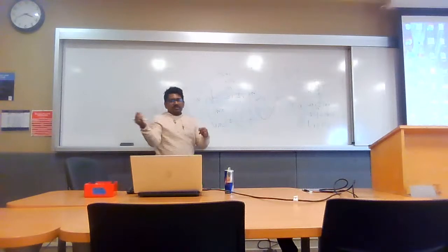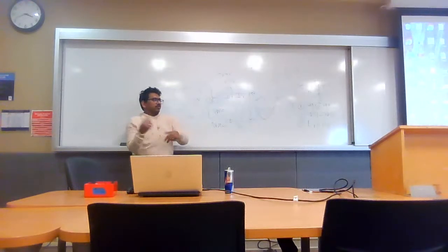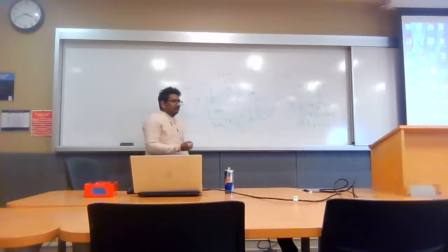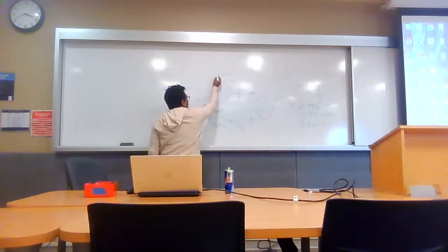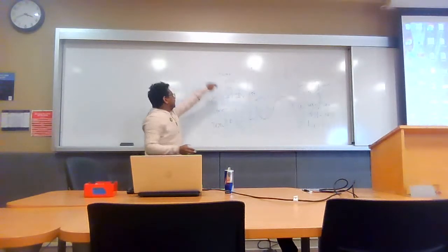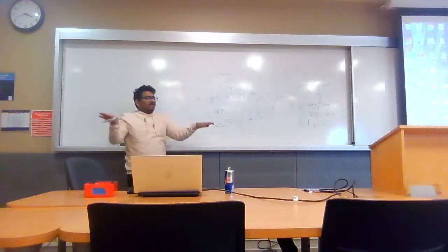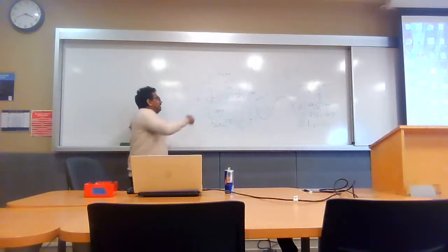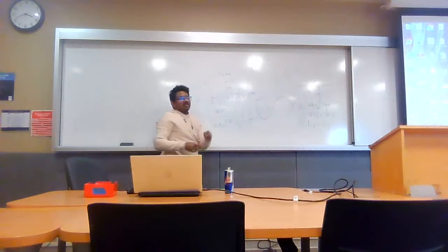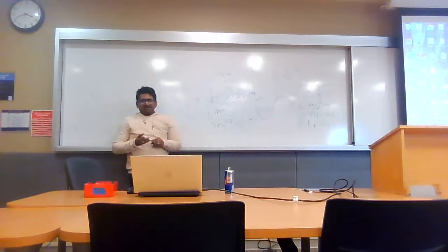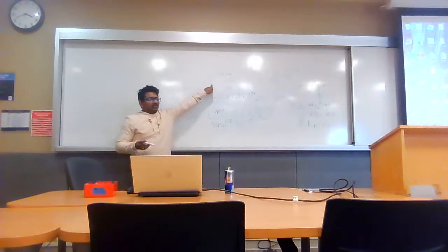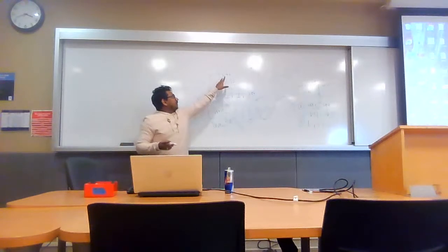In the reverse direction there is no current flow, but still there is a limit, and after some point there is a huge current flow, which means my circuit is gone. I think this point is known as avalanche breakdown. These points are also very important, because these are the very basics.